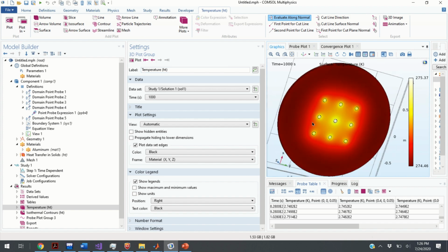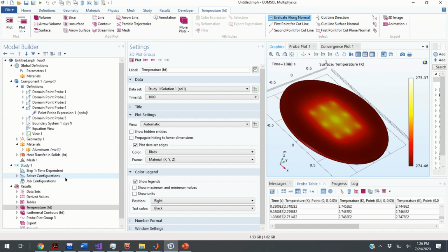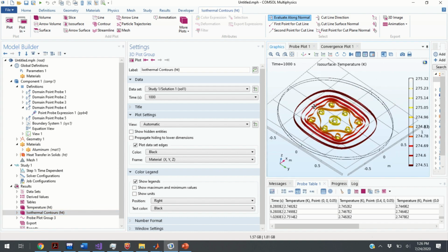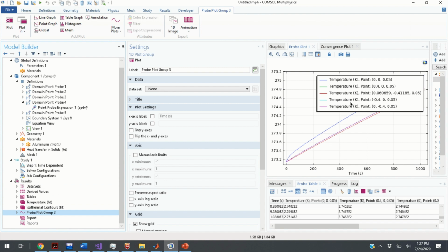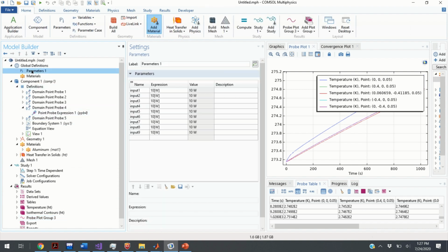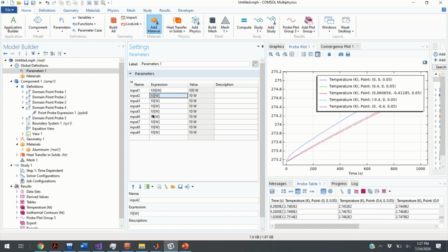So these are your results. So this is the temperature change, very small temperature change, since our parameters are input parameters. We are considering 10 watts, and here you can see the time responses at your probes. If you click here are the time responses. To get more visible temperature changes, you can specify here, let's say 100 watts. Why not? So let's specify a few inputs to be 100 watts, to insert more power into the system, and let's see what will happen.